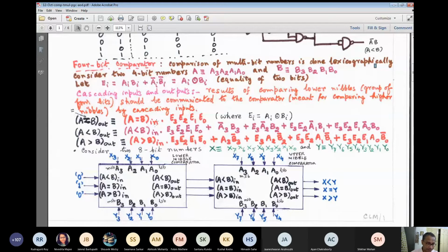Then they are ANDed. So I require a 5-input AND gate and 4 number of 2-input exclusive NOR gates. And here, how many do I require? I require a 5-input OR gate and a 5-input NAND gate. All this, and also the 4 number of 2-input equivalence gates are common to all these three, right? So overall, if you are asked to draw the gate diagram, draw the 4 number of 2-input exclusive NOR gates only once. Why only once?